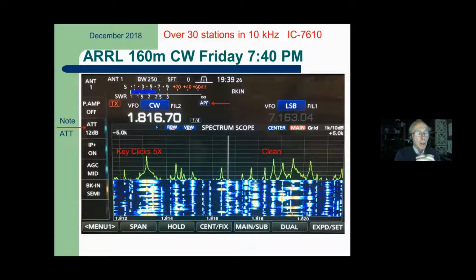If you're on 160 and 80, ground wave can be very good, and most people will use some sort of a top-loaded vertical on 80 and 160. And if you're running legal limit, and you've got a station even a few miles away, you can have a bodacious signal. So if there's any chance of overload, you can put in some attenuation.